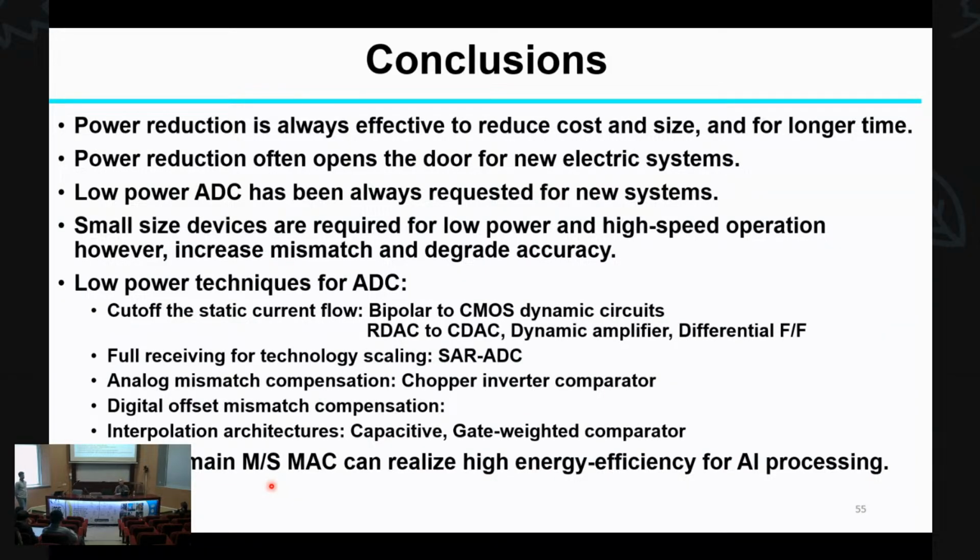So for such analog engineers, I think the design of the op-amp is the issue. A comparator-based ADC such as a SAR ADC can operate at 0.6 volt, because it is just a comparator.